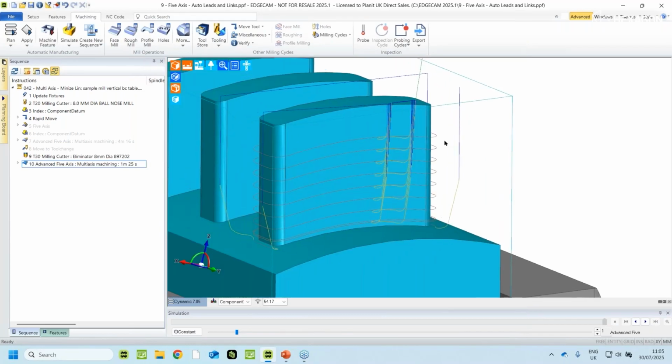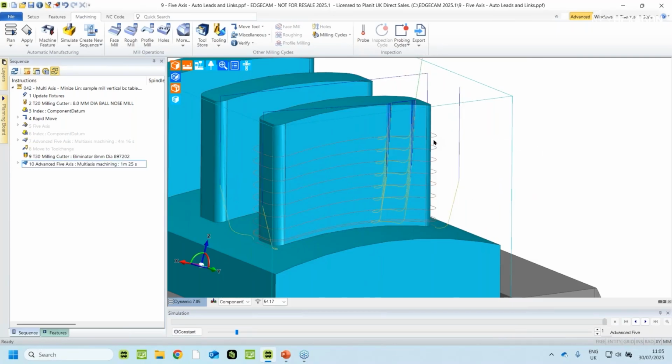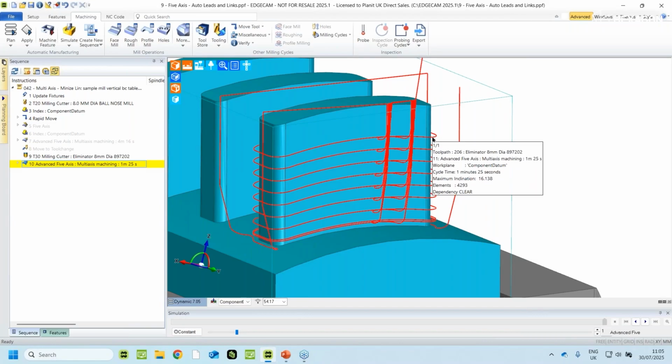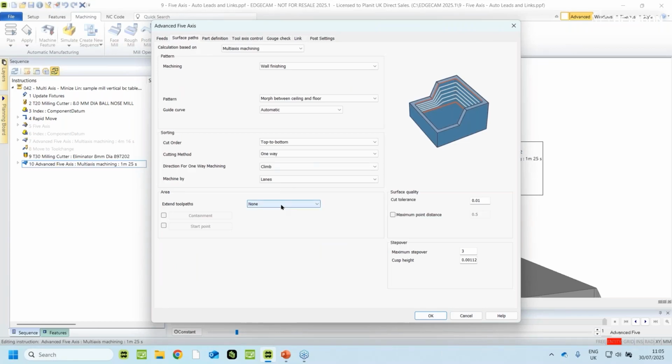The second item, in this particular case, I actually want to increase the toolpath time. What I want to do is when I join and exit the cut, I want to have a little bit of an extension, what we call extension or overlap in the profiling cycle. So in this particular case, it's given to us here in the extend toolpath area automatically.